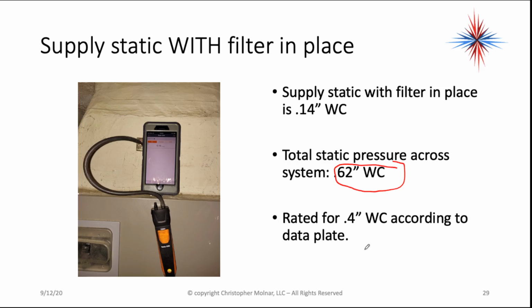So I do have a little bit of an airflow problem, but remember what I said. We have an ECM blower motor in there. So the blower motor is actually ramping up, and you could hear this when we put the panel back on. The blower motor is ramping back up and adjusting itself, speeding up to try to pull enough air through that filter for my static pressures and my ductwork. ECM motors will self-regulate a little bit, but as they ramp up, they use more power.